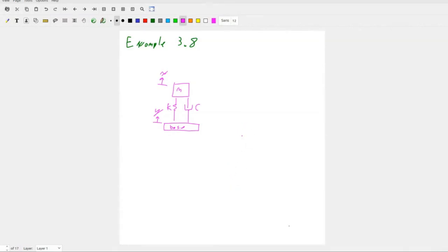And excited at the base, should the system be excited above or below the natural frequency if the transmitted force in the design is the design limitation? So we want to consider that zeta is equal to 0.1, the underdamped case, and zeta is equal to 2 for the overdamped case, right?